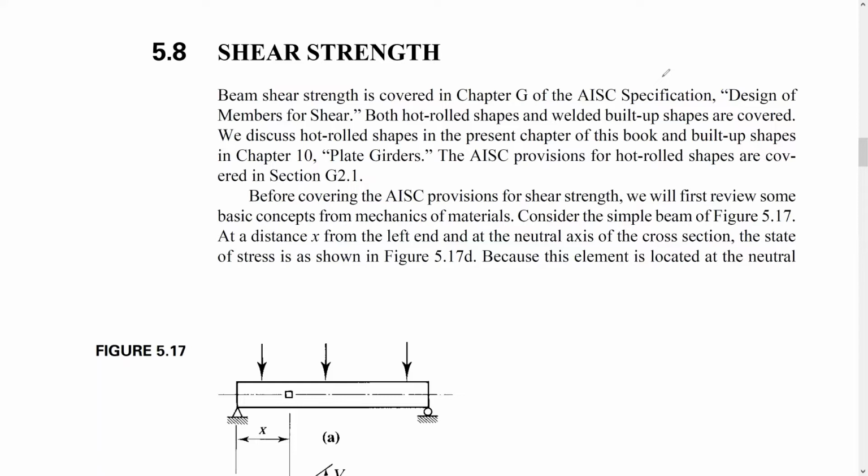The general practice is that you design the beam for the flexure strength, which is the moment, and then you check the shear to see if it's okay or not, along with the deflection. Of course, you know that in beams, all the time, if you make an imaginary section here, the main forces are shear and moment, okay? So it's different from the columns.